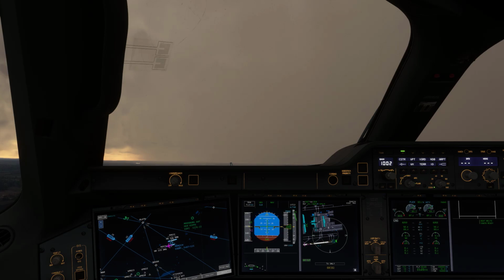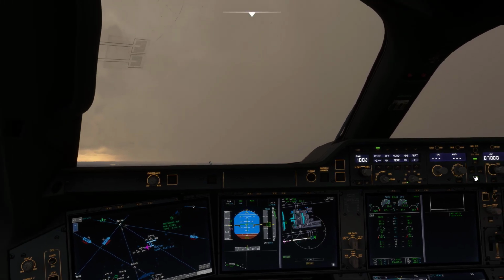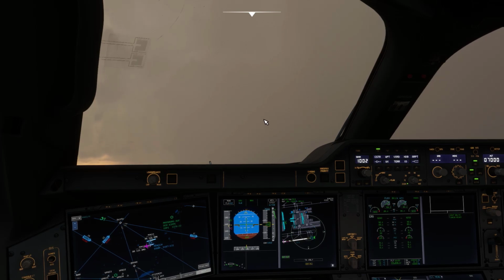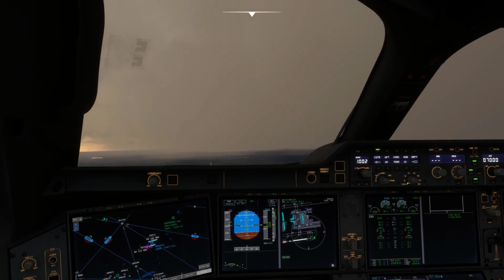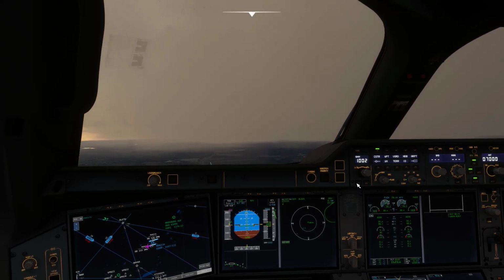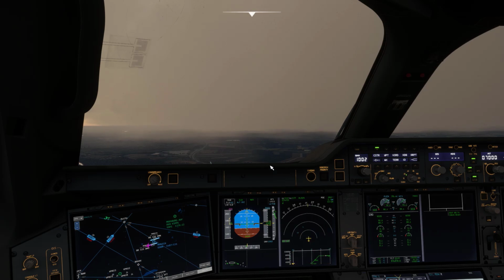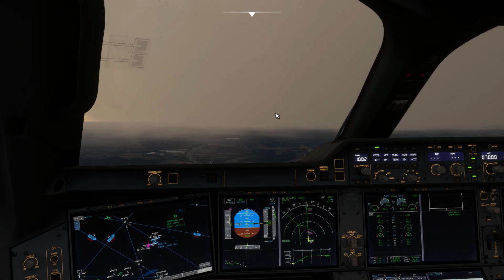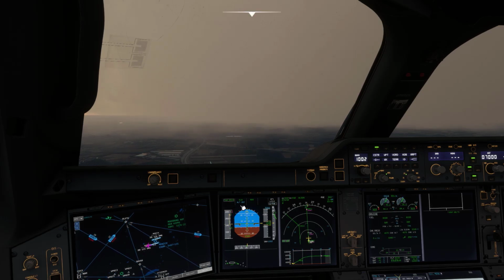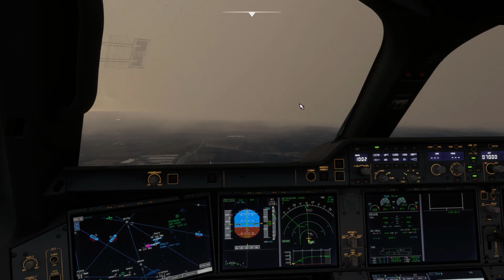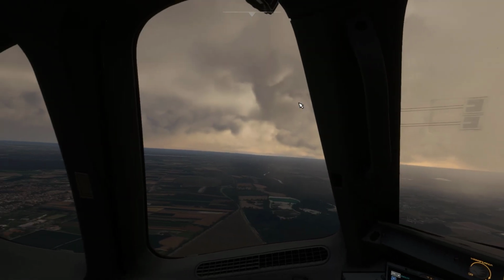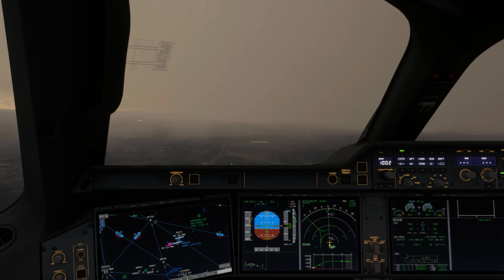And what I'm doing right now is I'm enabling the autopilot at this point. Let's see how that's going to work. Now I want to have that at 10, or maybe even 20, and of course on ARC mode. So here we are. Line departure, thrust climb, climb up, and the cruise altitude of 7,000, flight level 70 is dialed in. So there we are. Fine.